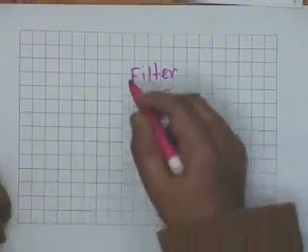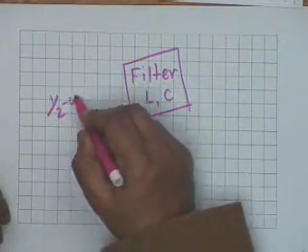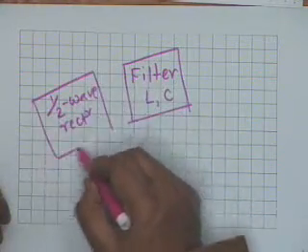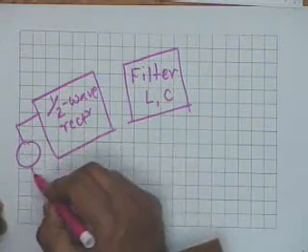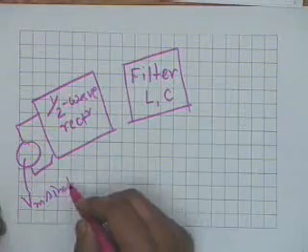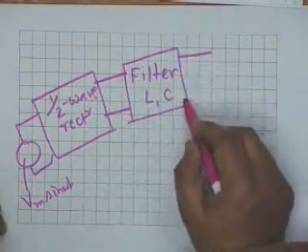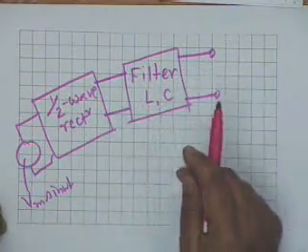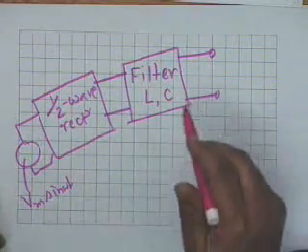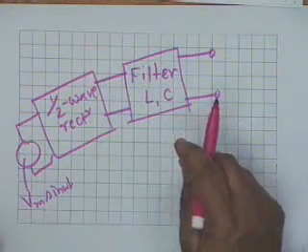It could be both. So, what we do is, suppose we have a half wave rectifier, which is connected to an AC source, Vm sin omega t. The output is passed through a filter, then the output of this shall be hopefully pure DC voltage, and this is what the power supply that you see in the laboratory gives you.